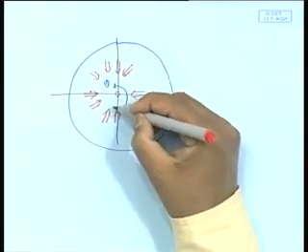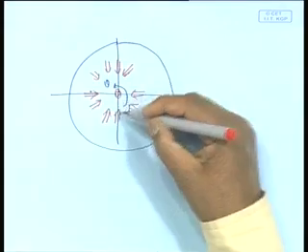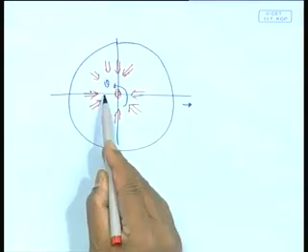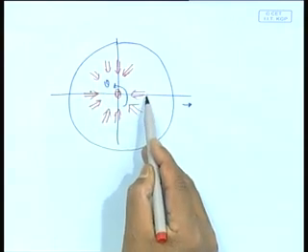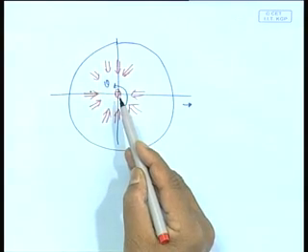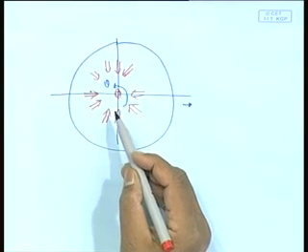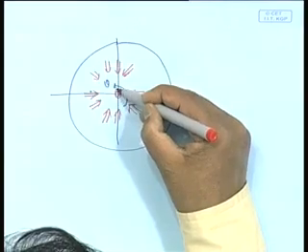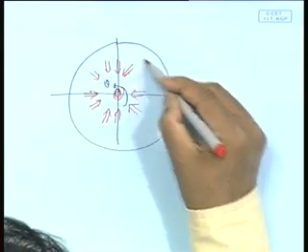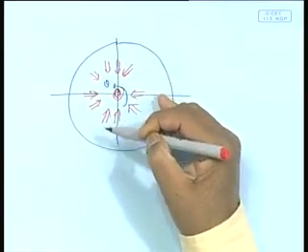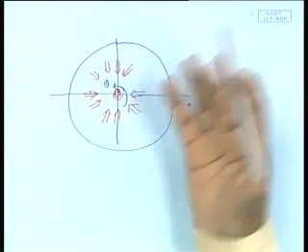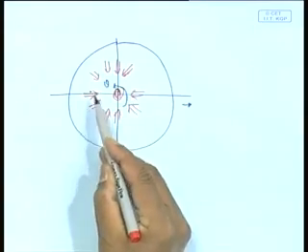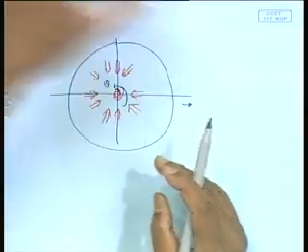So what I am saying is that the measured data consists of all the waves coming from all sides, but now there is a problem. Take this opposite, all the waves coming from this side and this side. What would happen if they are the same frequency? They would cause a standing wave, but however we have a progressive wave. So that is very important: we have to say that the waves coming are only over one half sector, because the other half sector is exactly opposite, and if I consider them I end up getting a standing wave. Or if it is a different frequency, see if I use this as A1, this as A2, I will end up getting a standing wave or a partly progressive wave on one side.